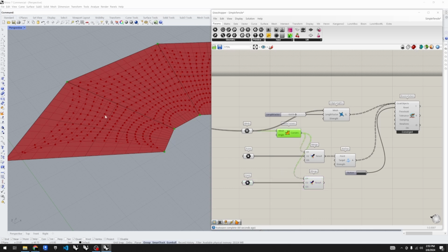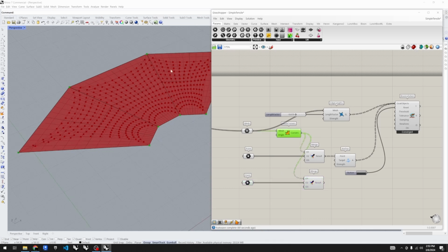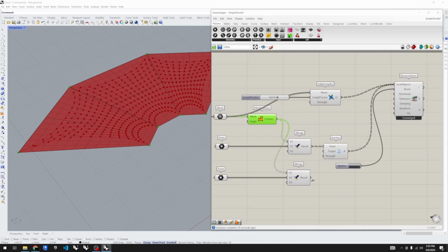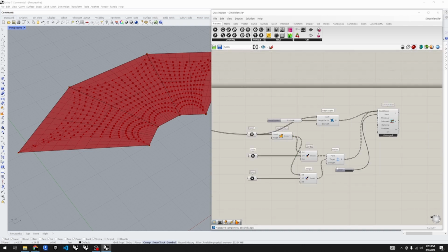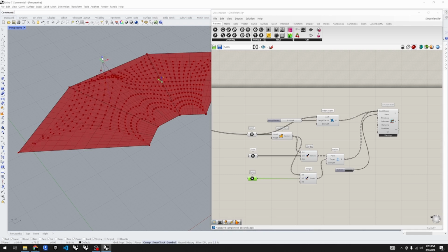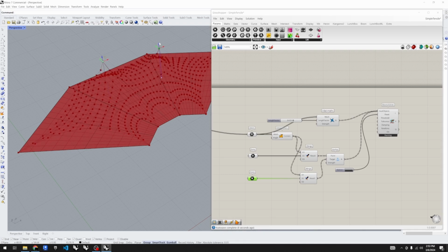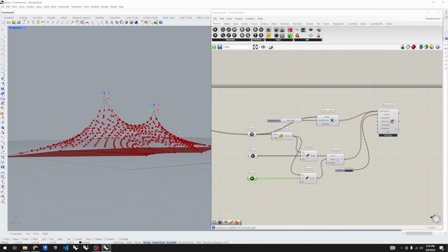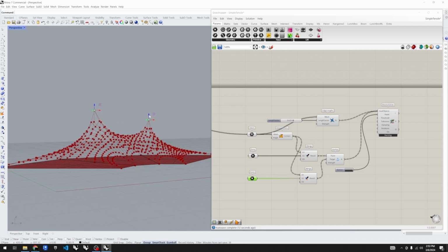since we're going to leave our corners where they're at to be anchored along the mesh, we don't have to put in a new parameter there. We can just leave our mesh corners. And what I'll do is bring this up to the targets. So now I can take my target and move this up and move this up. If I spin around, you see we're starting to get more of our tent structure.